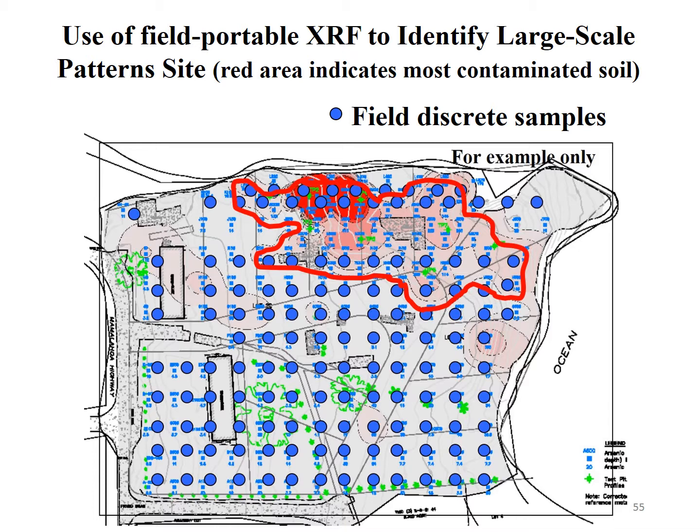And this was excellent. It provides good initial data, enough for you to use this data to start follow-up actions and planning for removal, planning for capping, whatever approach might be taken. However, there were some outlier points here. It's less clear whether they're really representative. Probably not a big contamination here, but nonetheless, that's the hazard of using a discrete sampling method, that you'll get these artificial cold spots or hot spots, and you don't quite know how to interpret them. Consequently, we don't use the field instrument for the final decision making.